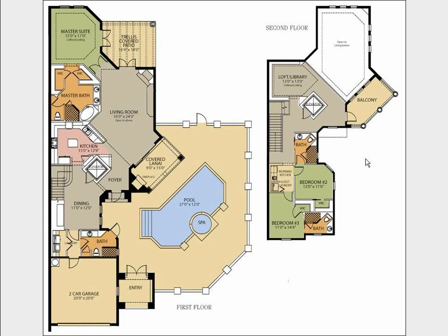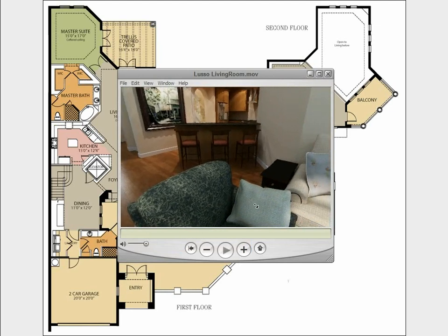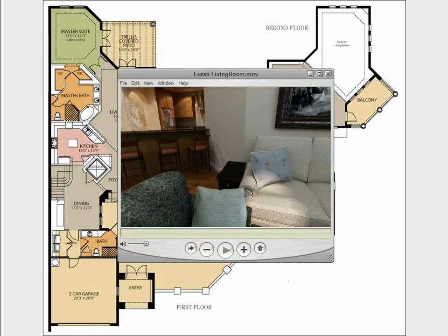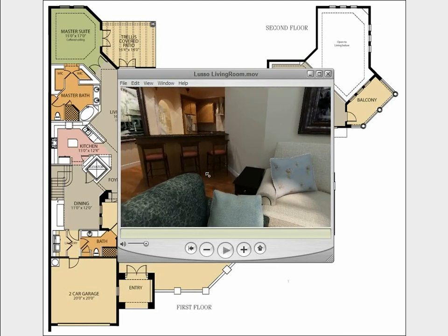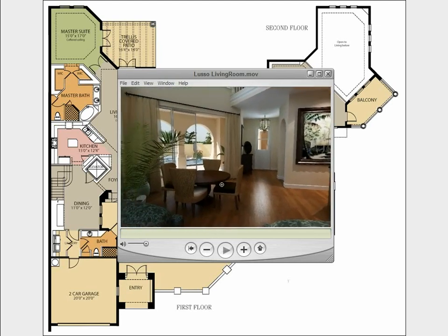Also notice in the panorama files that the rooms are fully furnished. These panoramas show the project completed, but in the max file that I'm going to be starting on, there's no furniture because, just like the excluded vegetation and cars and other things in Module 9, you really need to do the majority of your lighting tests without all the extra polygons that come with this furniture. Including it will only increase render times when you do your test renders, and besides this, I wouldn't usually even have the furniture to place in the scene at the time I start working on the lighting.